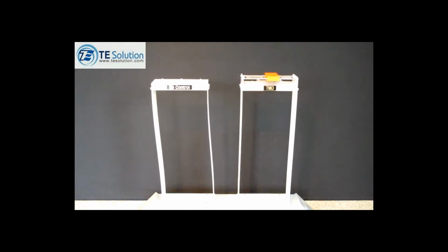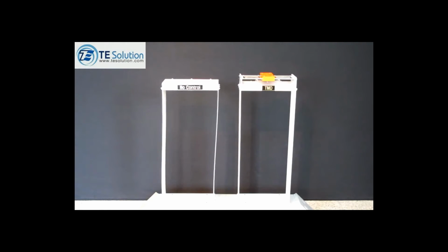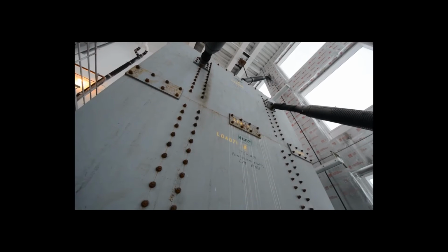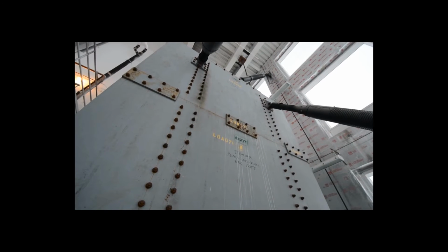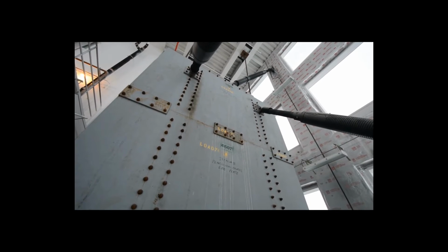To reduce the rate at which the structure starts to sway, 2 measures were taken. Firstly, the floor slabs in the top half of the tower were thickened to increase the overall weight. Secondly, 2 650-ton mass dampers were installed at the top of the tower. As the tower sways, the dampers move at different speeds to dissipate energy and reduce the motion.